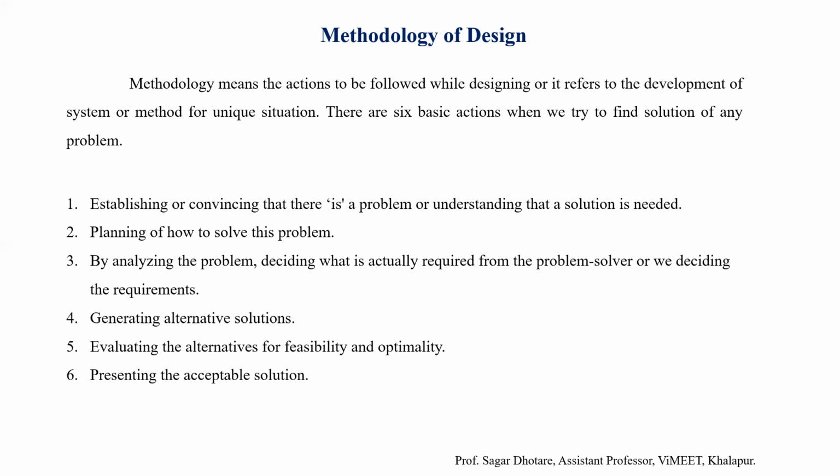Then also we have to consider the gear reduction point of view. What is the maximum speed, and how can we find it out? Then with the optimum space, how can we design that gearbox, because the reduction ratio is normally from 1440 rpm to 5 to 10 rpm. So how can we achieve it with the minimum number of stages.